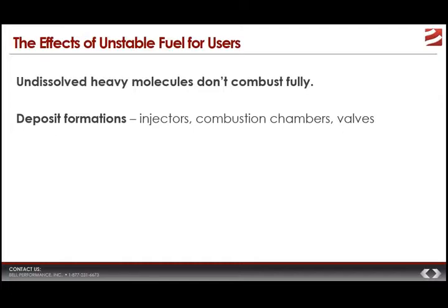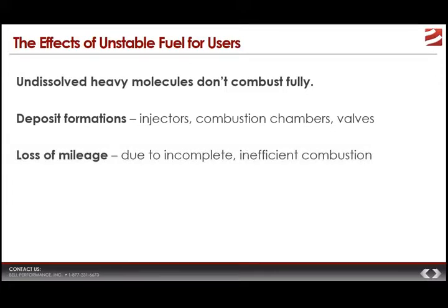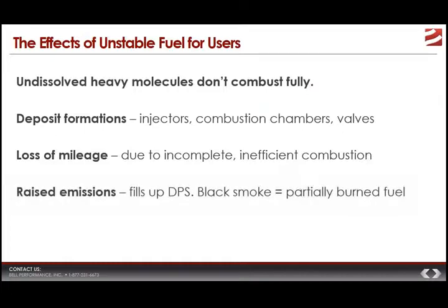And anytime you get deposits where they're not supposed to be, that's going to affect the performance of that equipment. And that leads to loss of mileage, both because you have deposits, but also because, as we were saying, these newer heavy molecules don't burn fully, so that portion of the fuel is not giving the maximum amount of energy and maximum amount of work that it's supposed to give.